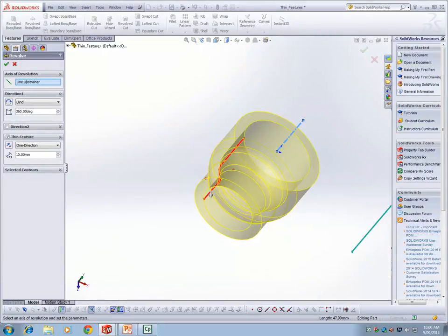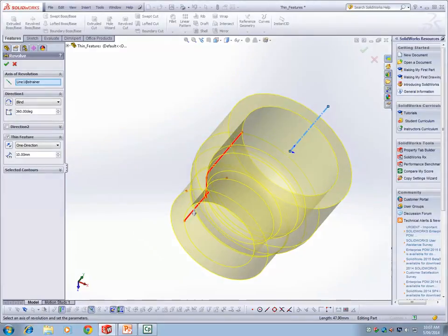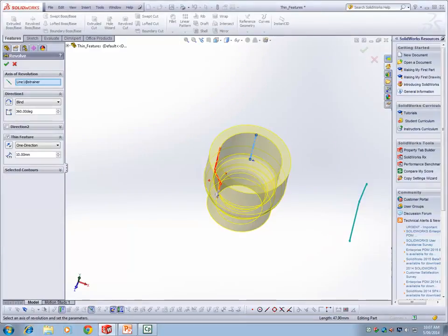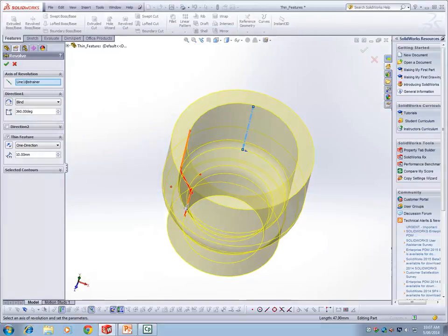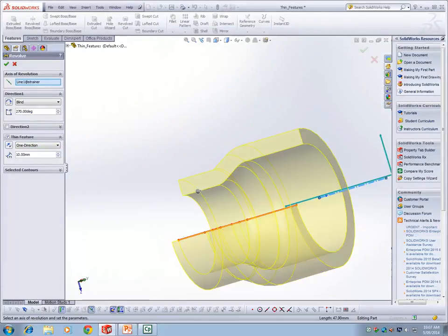So apply the thickness here, whatever the thickness specified in the model. It looks like a ratchet head, so it has certain thickness, apply that thickness, and you can also use the direction or the mid plane. You can eliminate that. Okay, along the extrude.